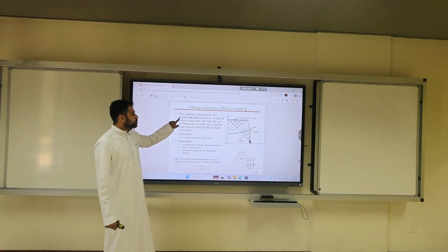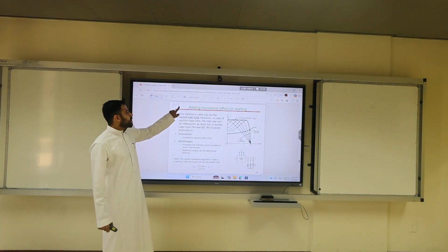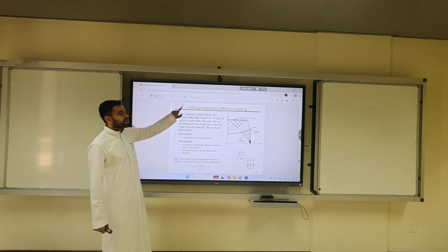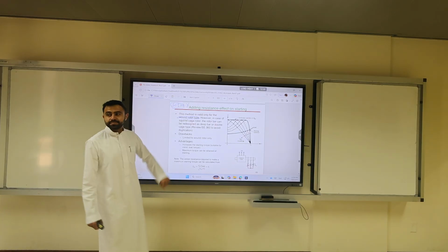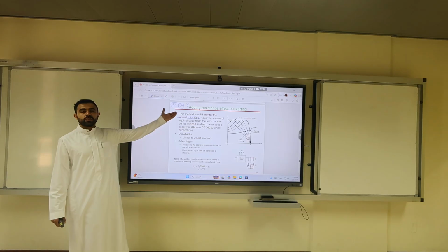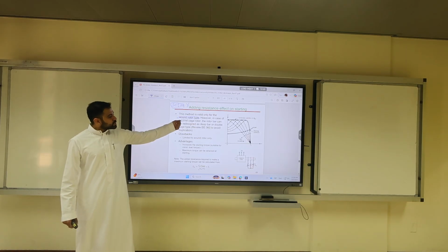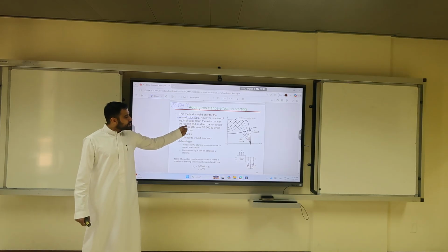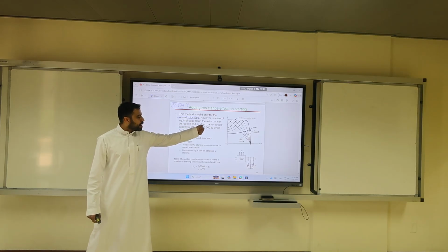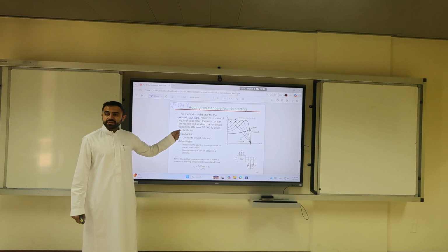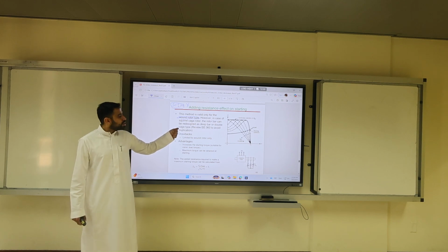Wound rotor. So for squirrel cage IMs, it is not applicable. And the vast majority of your motors are what? Squirrel cage. In the case of a squirrel cage rotor, the rotor can be redesigned as a deep bar or double cage type. This is the solution for squirrel cage.